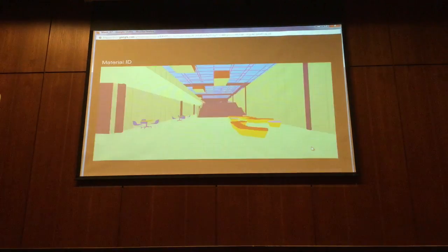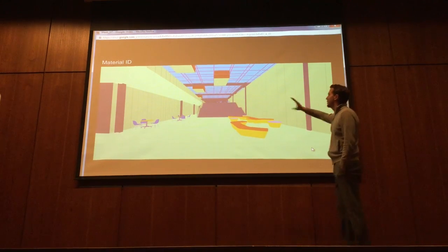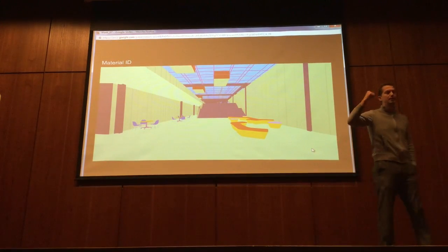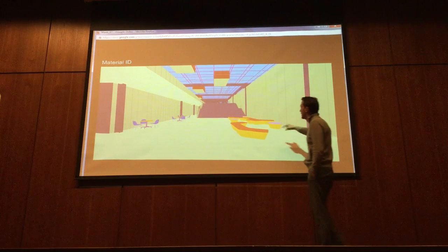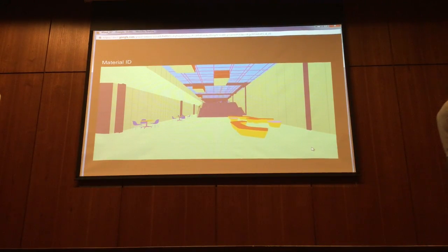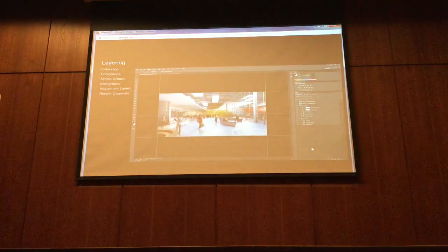Right. So if we look at material ID, these you set, and you have to take some time and some initiative to do this, but the reason why you would do this, and we'll see a slide later where they're properly placed in Photoshop, is now I've got all of my materials set in my rendering, I've rendered it, and I've got a selection map I can use in Photoshop. I can select this particular color and only select this area, and then I can manipulate that section, right? I can render the stair whatever color I want the stair to be, and because I have the purple layer there, I can just select that exact color and constantly change just in Photoshop what I want it to be. I can make the glass a brick wall, you know, and just do that all in Photoshop.